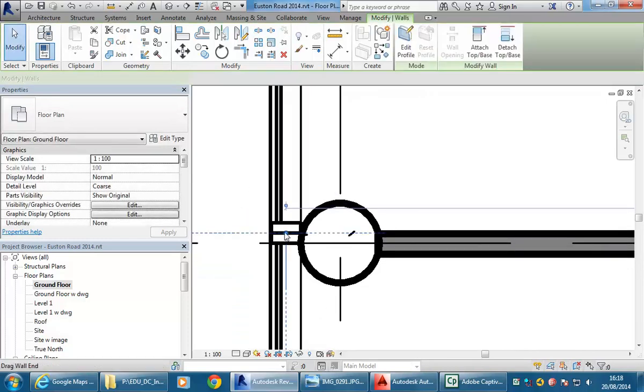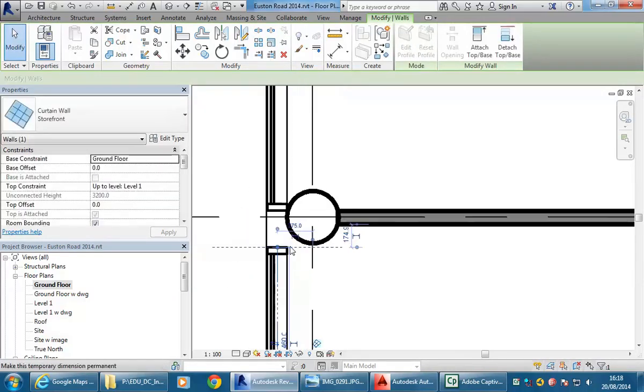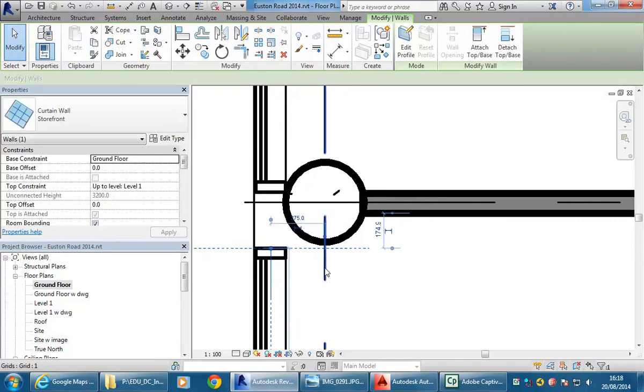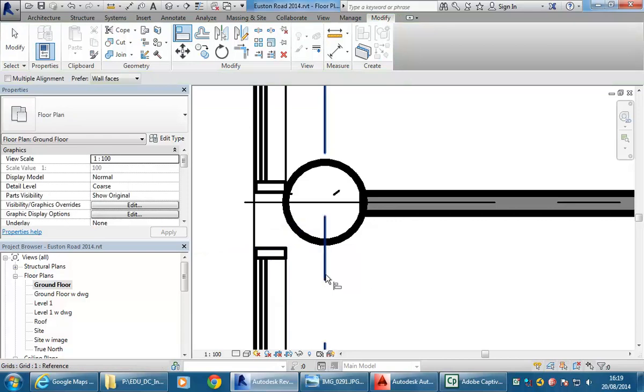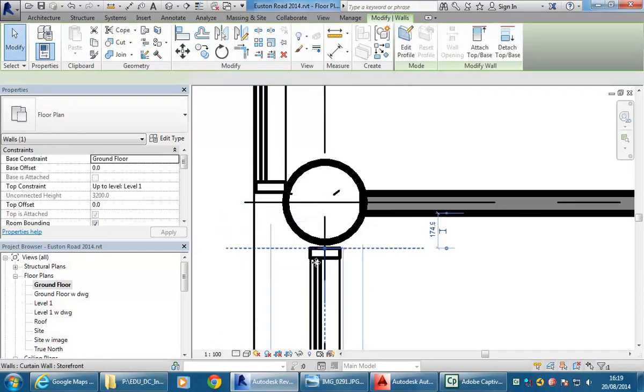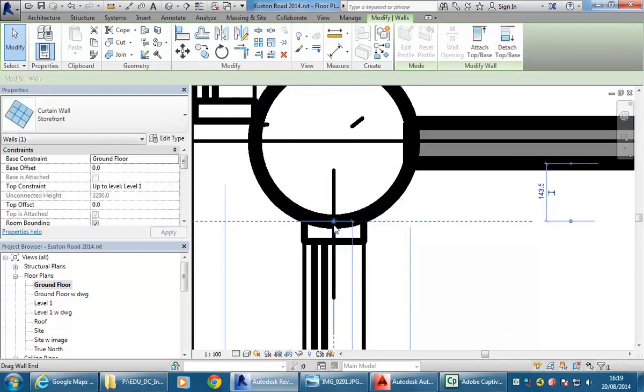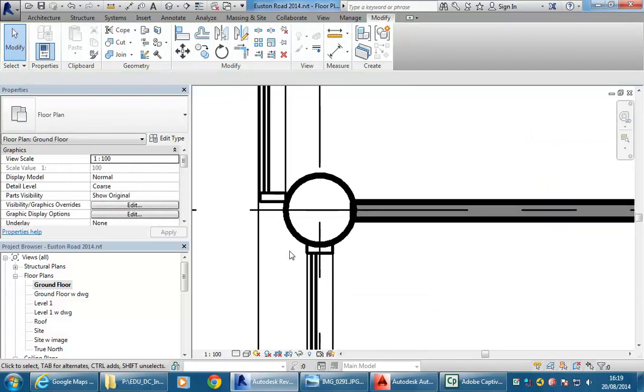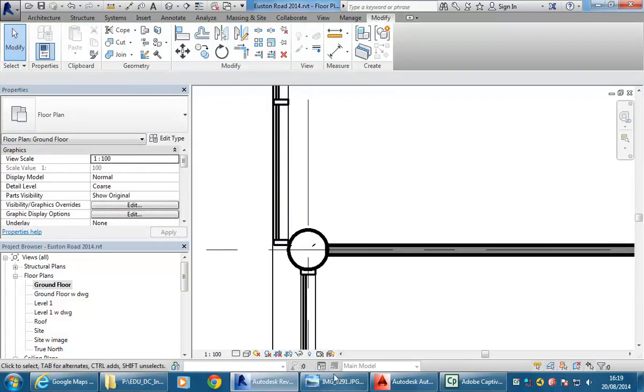and again drag the end of this away, and I'm just going to try using a line. Yeah, that should work pretty well. With a line I can line up with the grid line, then try stretching this to get it fairly close to the column, and that will give me a pretty reasonable join. And so then I'll do the same with the next one. Even though you can see it probably slopes or goes at an angle there, I'm going to ignore that and just do it in line with the column.